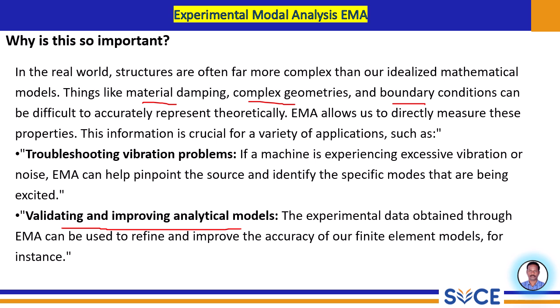If there are significant discrepancies, it tells us that our model needs refinement. Perhaps we need to adjust material properties, update the boundary conditions, or even refine the mesh. The iterative process of experimental validation and model updating leads to much more accurate and reliable predictive tools, which are invaluable for future design iteration and optimization.